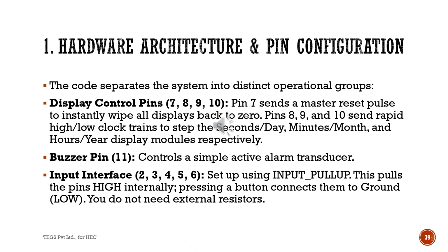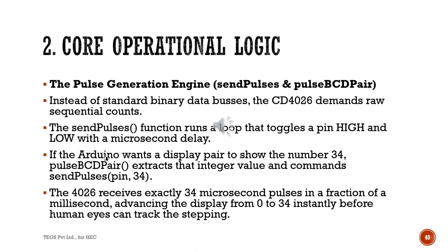Input interface pins 2, 3, 4, 5, 6 are set up using input pull-up. This pulls the pin to high internally. Pressing a button connects them to the ground, low. You need not externally wire a resistor.